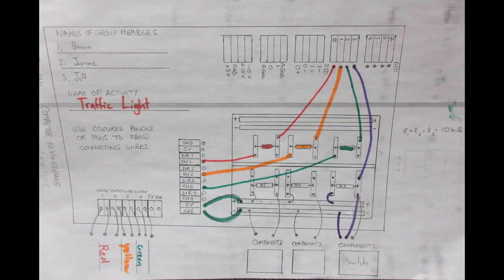In order for the lamps to be powered, they must each be connected to an output. Connect the red light bulb to output 1, the amber light bulb to output 2, and the green light bulb to output 3. Then use the wires to connect digital output line 0 to enable 1, digital output line 1 to enable 2, and digital output line 2 to enable 3, ensuring each circuit contains its own 10K resistor. The lights are now powered.